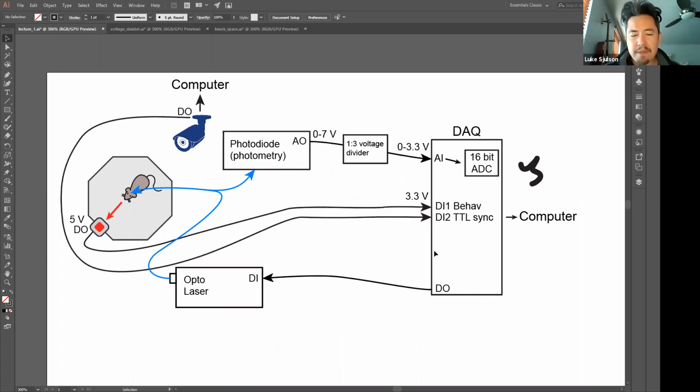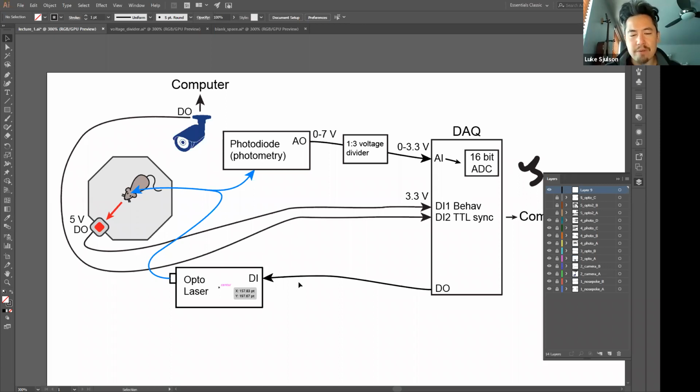Okay, so analog output, for example, would be that instead of just giving pulses of light, you want to give, say, a sinusoid or white noise stimulation or ramp or some sort of analog function. So in theory, you could do that with pulse width modulation and so forth, but in practice, you can actually just use an analog control.